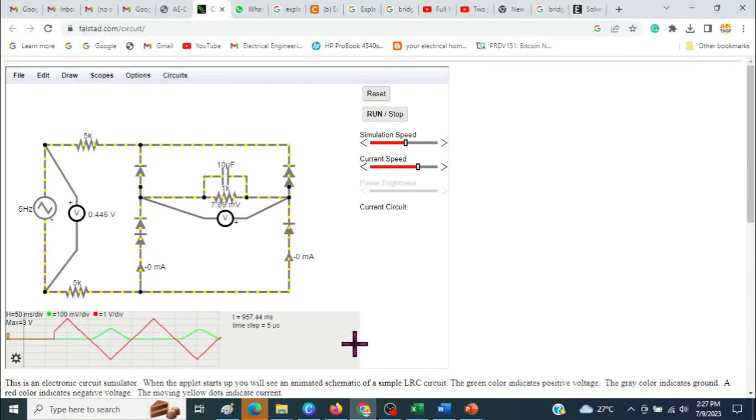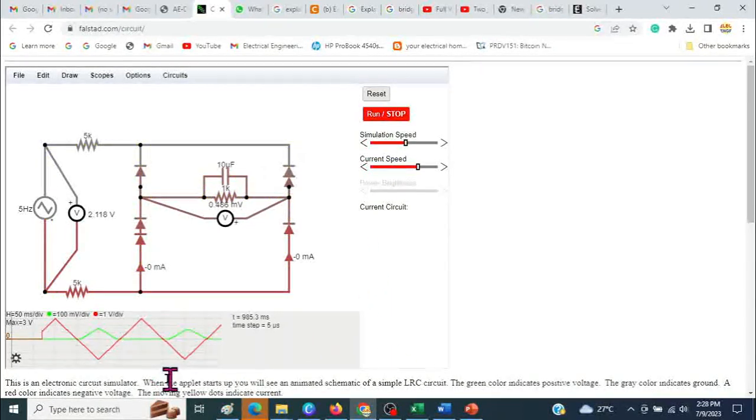As you know from the full wave rectifier, when we add a capacitor, we call it filtering. It tries to smooth the output. So that effect is happening here. And also it took slightly more time. Now look here. This finished here at this point, but this one is finishing almost at the end. So it took slightly more time to discharge. It started late and is discharging late because of this current, the discharging of the capacitor.